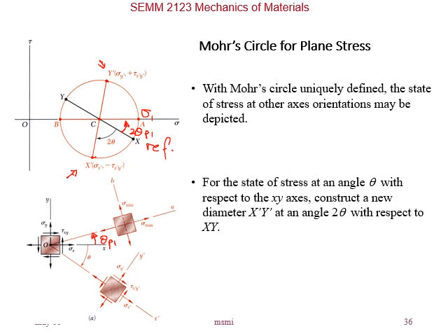You want it to be clockwise, theta. Therefore, in the Mohr circle, draw 2 theta. And then you get this line, draw the line. If you have graph paper, then you just read the value of the coordinates. If you don't, then you have to do some calculation, okay, based on geometry. So we just draw clockwise from the reference, angle theta, and we get a stress element.